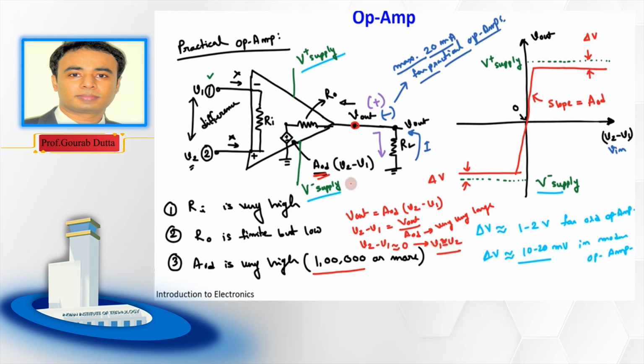So that means for this op amp, the potential here at V1 and the potential here at V2, the op amp will try to arrange these two potentials such that, in a closed loop operation, this V1 potential will be close to that of this V2.